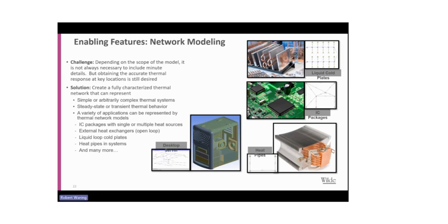This versatile approach enables the representation of a wide range of applications, from IC packages with single or multiple heat sources to external heat exchangers, liquid loop cold plates, heat pipes, and more. The challenge lies in achieving accurate thermal analysis while managing the computational complexity. In many cases, including the fine details can be computationally intensive, leading to longer analysis times. However, obtaining accurate thermal responses at specific locations remains essential for comprehensive analysis.